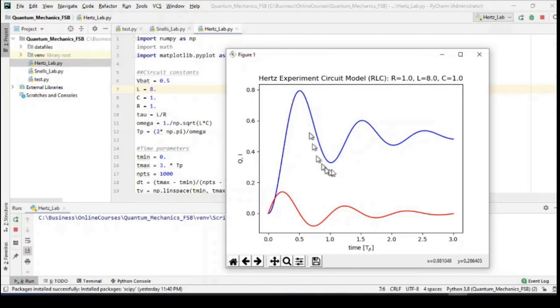And so this is what the charge looks like. The charge bottoms out here. We went back to 0.5 for the volt for the battery source, and so it's settling out at C times V. If you recall the solution that we had, it's going to settle out at V times C. C is 1, so it's going to end up at 0.5. So this is just oscillating before it settles down to a DC charge on the capacitor across the gap. But before it actually accumulates all of the charge, there's going to be some oscillations which are enough to excite this AC electromagnetic field and cause sparking in the gap.